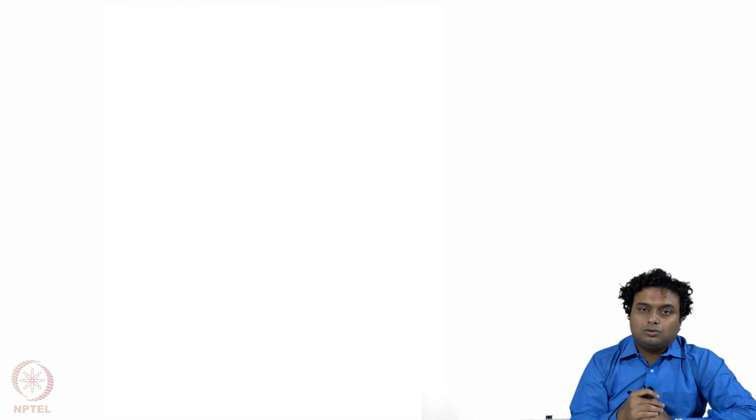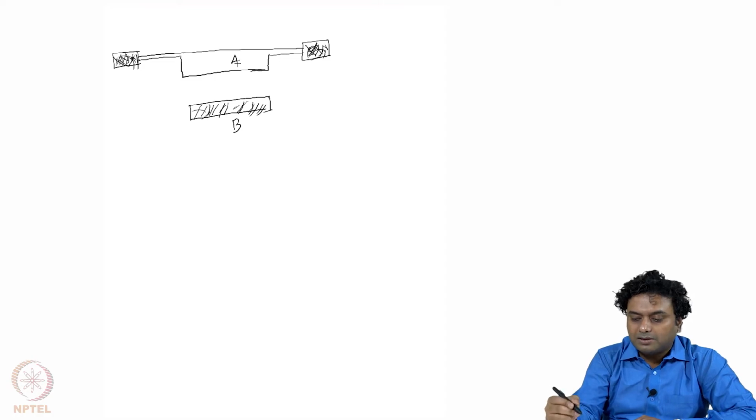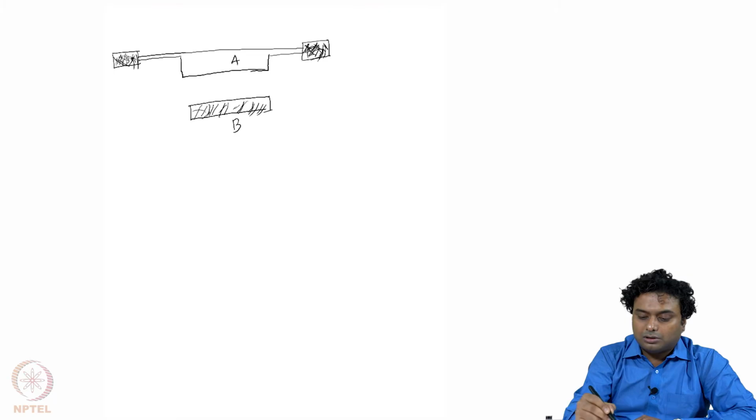Now, once we know some basics of electrostatics, we will try to couple the electrostatic force with the mechanical force we learnt in our previous modules. Okay. So I am first drawing two different cases. So this is a fixed plate, let us call these A and B. A is a plate which can move, and this is supported by two beams which are connected in the opposite direction to a fixed support, as shown by this shaded area, and this B plate is already fixed at the bottom.